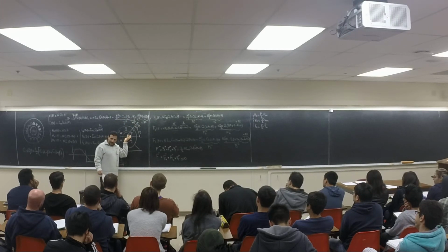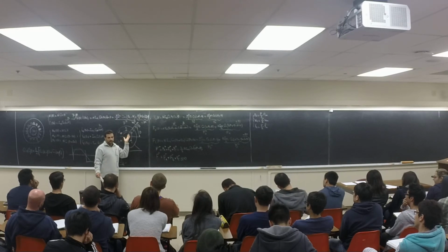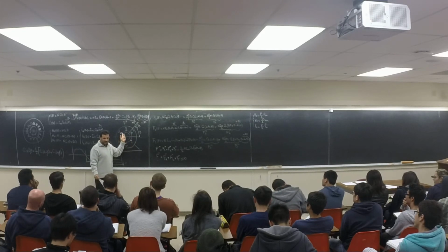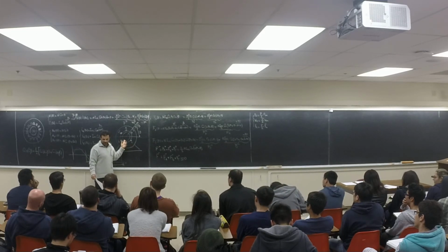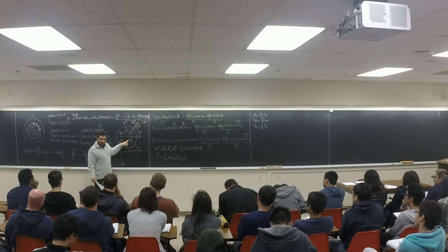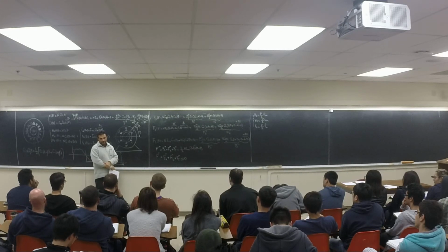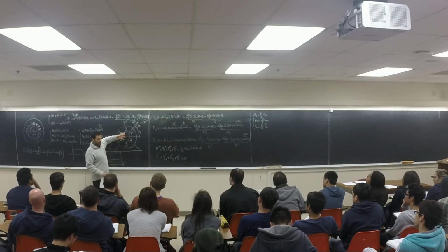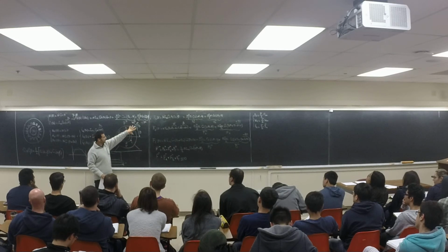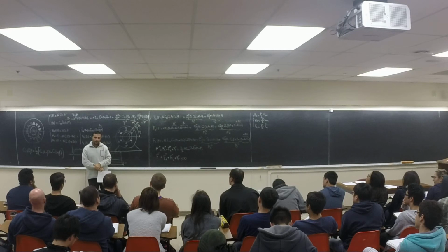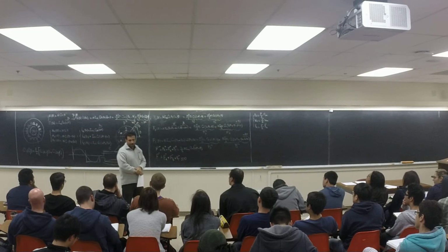I myself am the prime mover for this rotor, and I'm going to rotate it with 50 hertz, right? So the speed of this rotor is going to be 50 hertz, mechanical speed. So the winding inside this one, what kind of frequency do you have? See, this machine, we are rotating it with 50 hertz. We have 60 hertz here in the stator. What frequency do you have? 10? Hmm? 10.